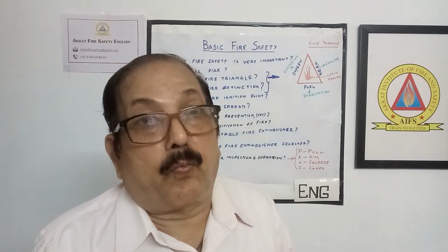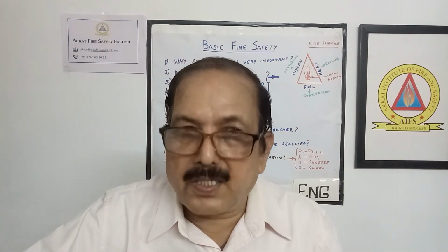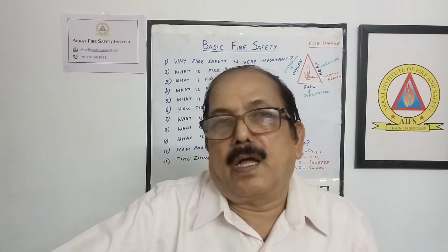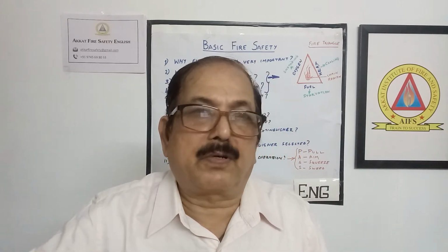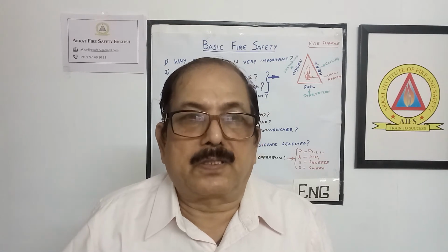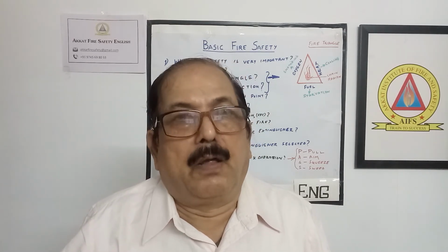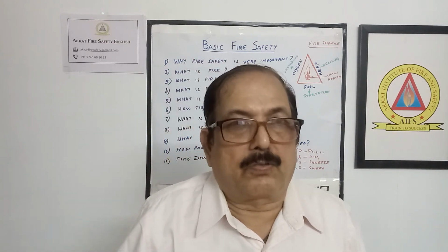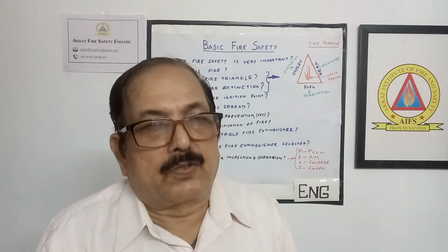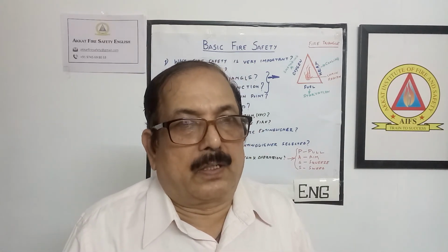But in the case of a foam extinguisher, you need not sweep it. There is some hard surface there, where you have to jet the foam so that the foam covers it. But if you are sweeping, what will happen is that the oil and other flammable liquid will be disturbed again, and it will not get extinguished immediately. So this also you have to remember. So this is the way you have to operate the fire extinguisher.